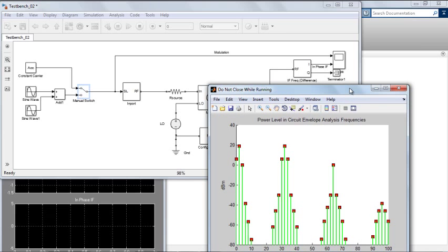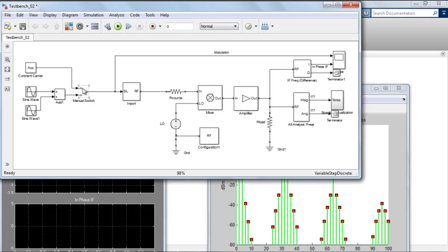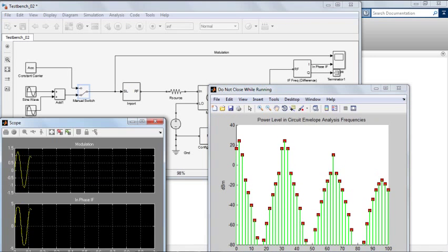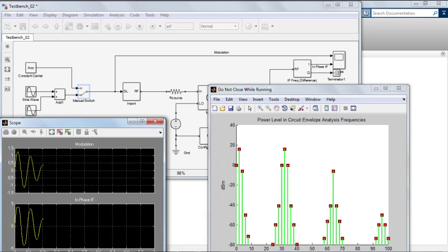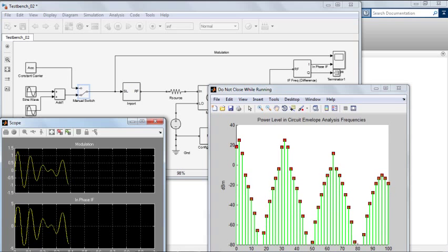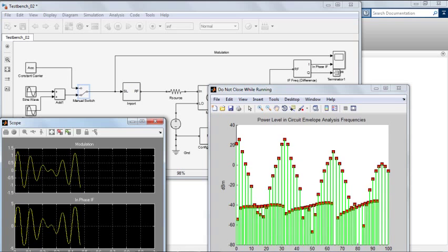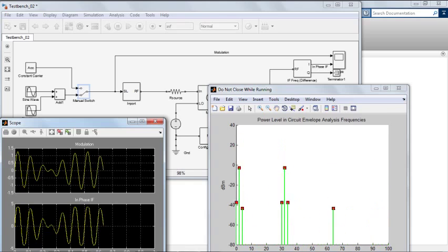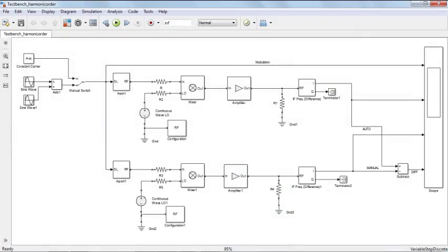We can also visualize the impact of a time-varying signal amplitude in the frequency domain and determine the harmonic order to achieve correct results for a given peak power. This setup helps us validate the results and the choice of the harmonic order. Harder nonlinearities and larger signals will require a higher harmonic order. By looking at the simulation results in the frequency domain, you can get an estimate of the correct harmonic order. If the energy of the generated harmonics is evenly spread in the spectrum, you have chosen a harmonic order that delivers correct results and that is a candidate for further reduction.